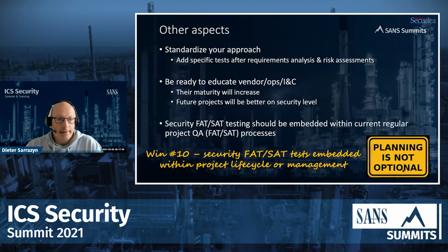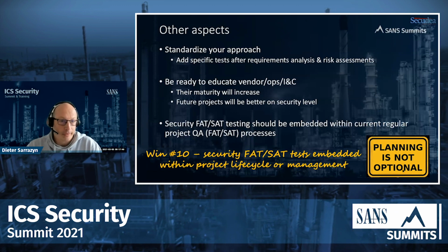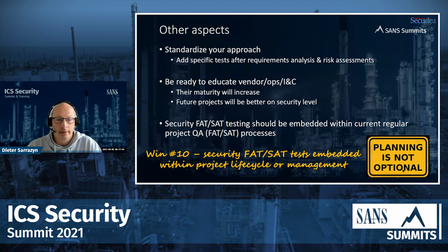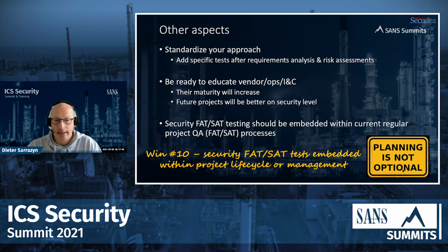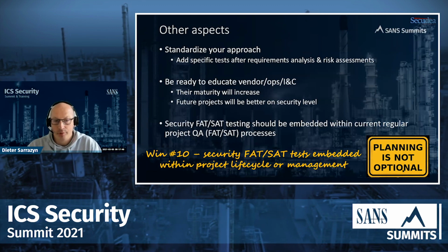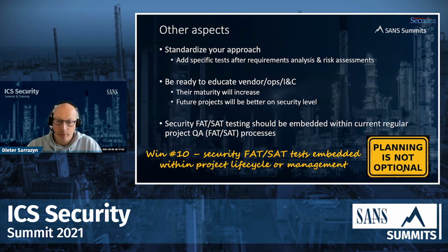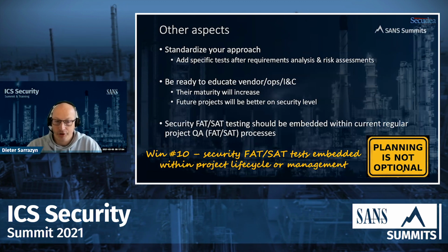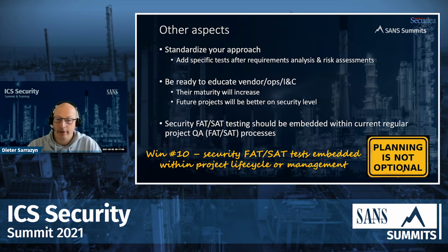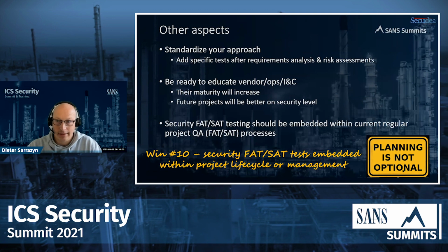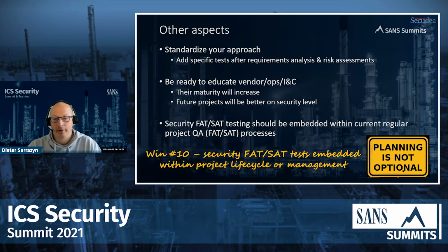Other aspects: standardize your approach. Be ready to educate vendors, operations, and IT, and embed cybersecurity FATSAT testing within project quality assurance processes. The biggest win is that security testing should be embedded within every single project lifecycle or project management lifecycle. Planning of security testing is no longer optional in my point of view.